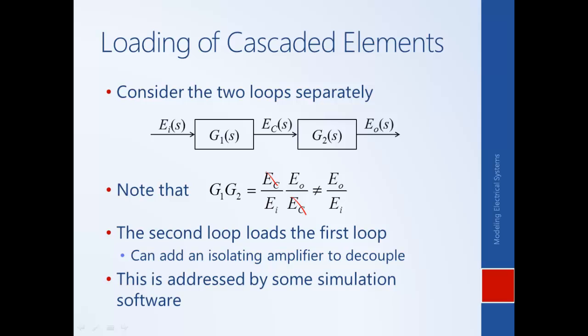This idea is addressed by some simulation software but not others. In particular, simulation software that is called physical modeling tools, or that actually are aware of what's being modeled, for example circuit simulators like PSpice or SimPower Systems, actually know that what's being modeled is a circuit and will take into account this loading effect.